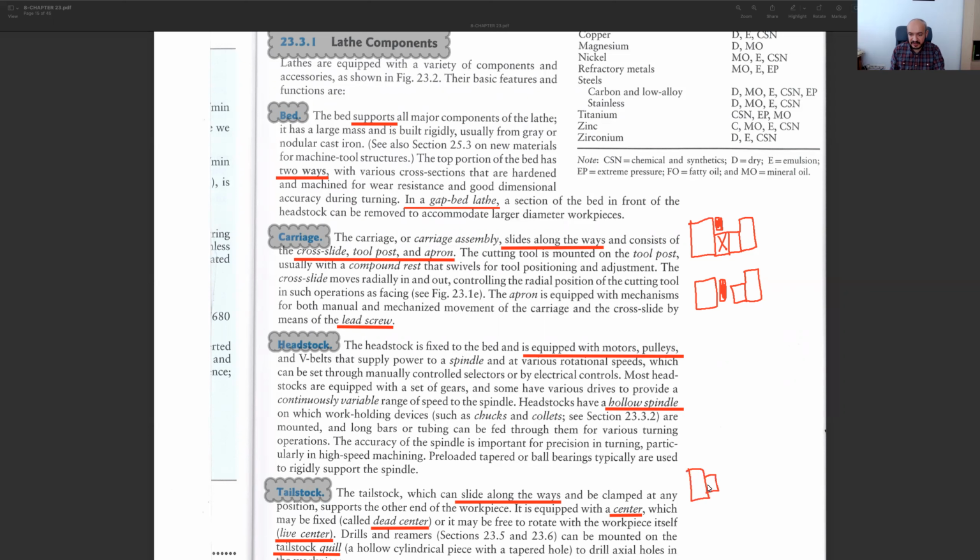You have your workpiece rotating, and assume that these are some rays of your tailstock. This is the tailstock, and this is the headstock. You may have some specific cutting tools. For instance, you may have a drill or a boring tool, and then you can move it in this x-axis and try to machine your workpiece. So it's also possible with the tailstock.